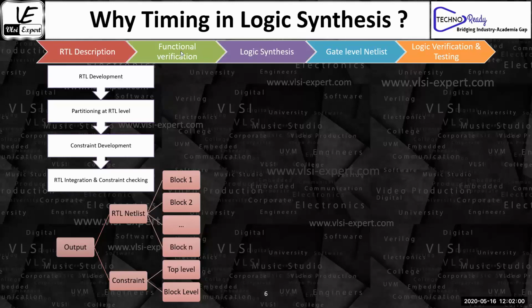Like I gave an example, 1 nanosecond or 0 nanosecond: on what basis have you defined it? Because if there is a wire which connects directly to your block, that means 0 nanosecond. If there is a connection through a buffer, that particular buffer will have a 1 nanosecond delay, and you can see the net delay as the stage delay. So that becomes a constraint for that block, like okay, after 1 nanosecond.